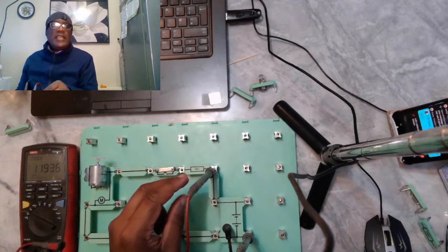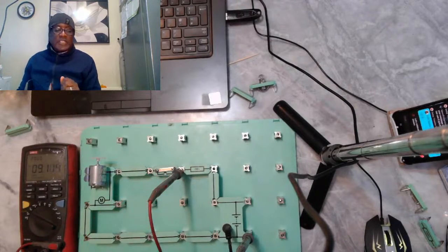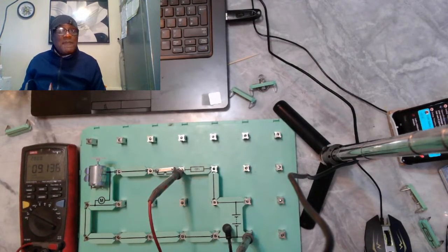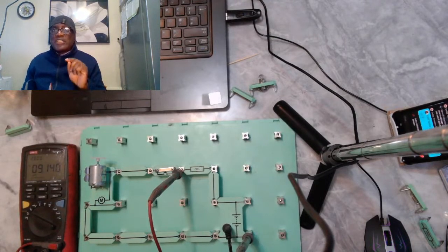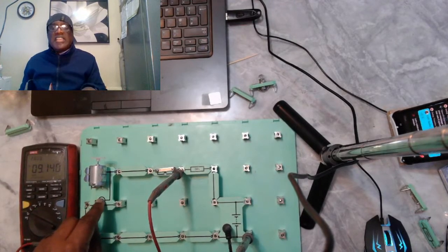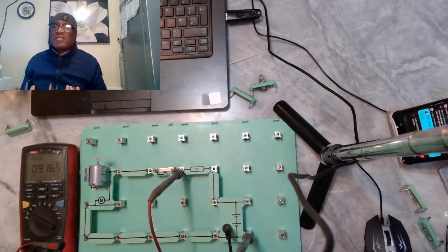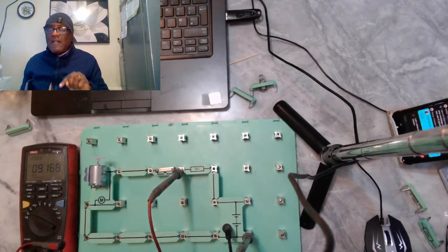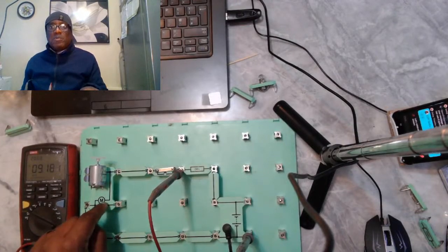So here we go. Let's see, 11.93, 9.1. That's a big drop. You want to investigate that. Okay, that is a big drop. You want to investigate that and make sure that you know what is causing it, because it has become an additional resistance, unnecessary resistance, unengineered resistance that we do not want, which is affecting what we are doing with this motor.